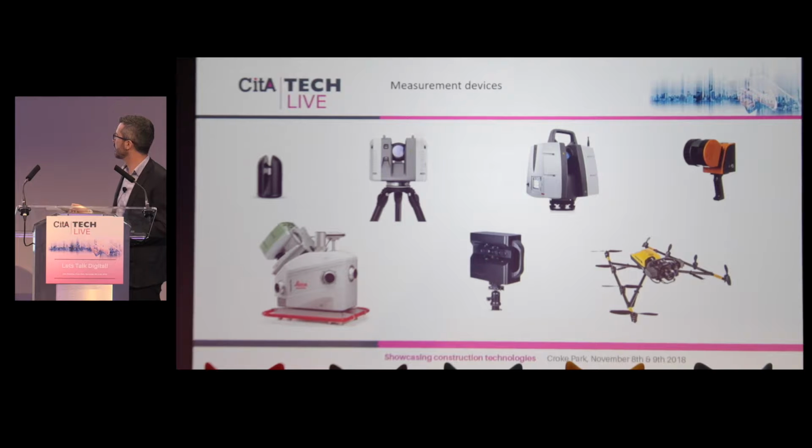But there are also 3D cameras that use a combination of lasers and images to capture 3D information. And like Gerrit was saying, UAVs are also a survey tool these days. The UAVs are mounted with a camera that captures a lot of digital photography of the environment. With that photography, we can apply photogrammetry techniques, structure from motion techniques, and the output of that is a point cloud.